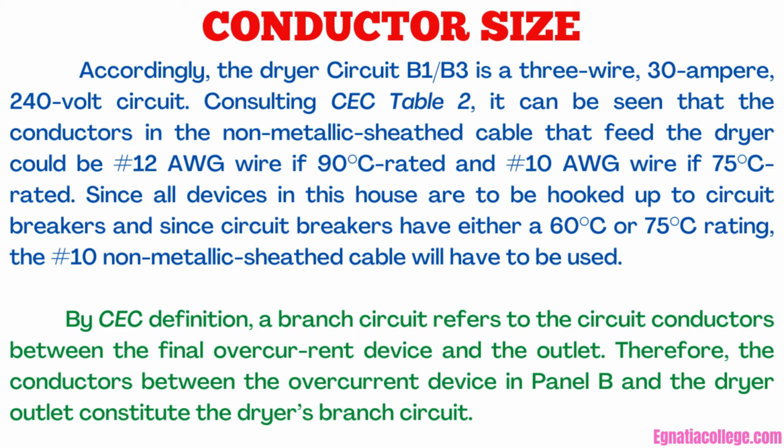By CEC definition, a branch circuit refers to the circuit conductors between the final overcurrent device and the outlet. Therefore, the conductors between the overcurrent device in panel B and the dryer outlet constitute the dryer's branch circuit.